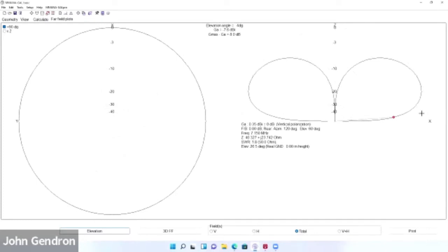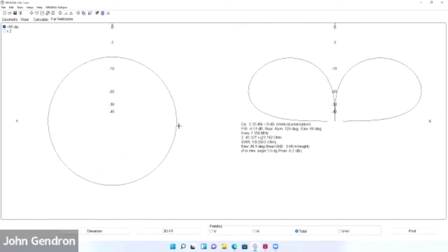It just depends. Okay. But again, we're getting a little bit off topic, but we can take a look at this and say, okay, we want the elevation at 5 degrees. We change that calculation, and you can see that circle shrunk, right? Now we're seeing negative 6 dBi, 6.2 dBi in that circle. Now, that's just a layer of that elevation, right? It's not the whole picture. It's not that whole 3D model. It's just a layer, right? So we cut it at 5 degrees off the horizon versus 26.5 degrees off the horizon. Does that all make sense to you?